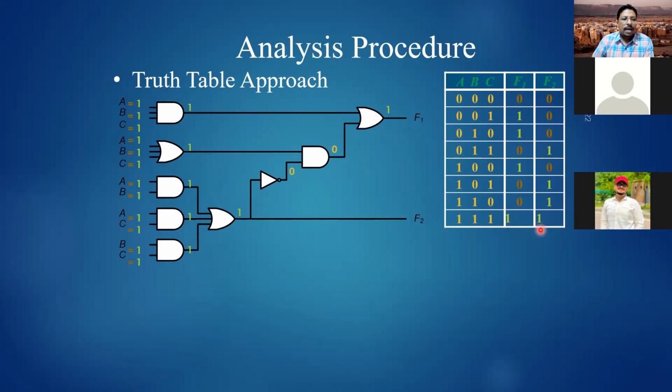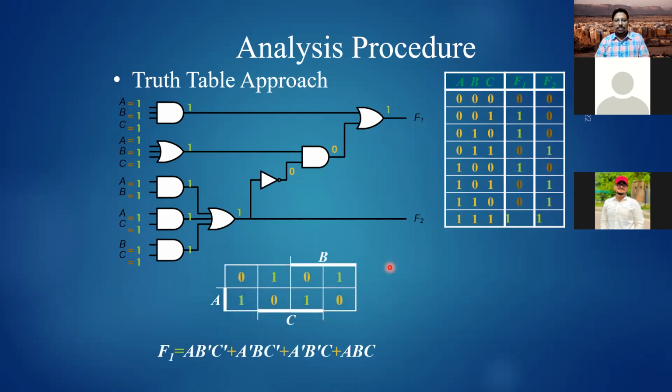Now, what do I have to do after this? I have to build my K-map. Now I have F1 and F2. F1 is available at 1 and 2, right? When I make the square map, as there are 3 variables ABC, I have 8 squares, right?